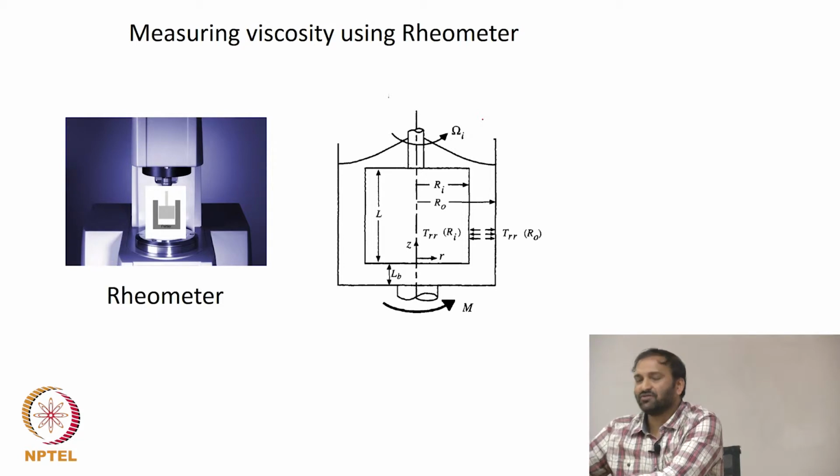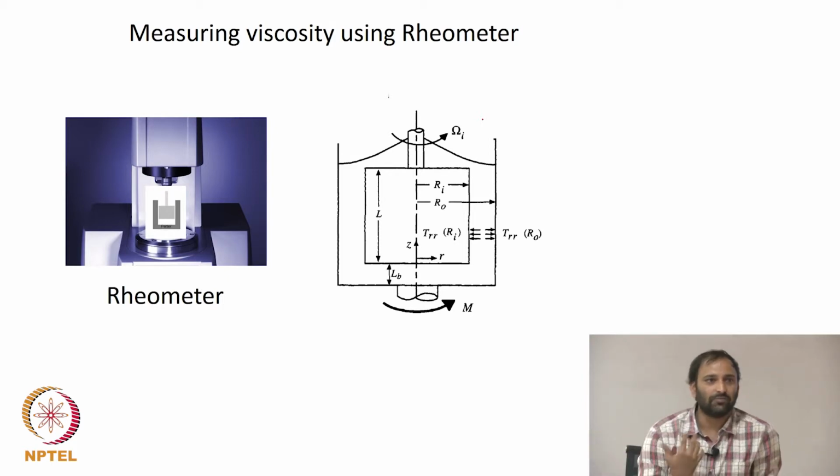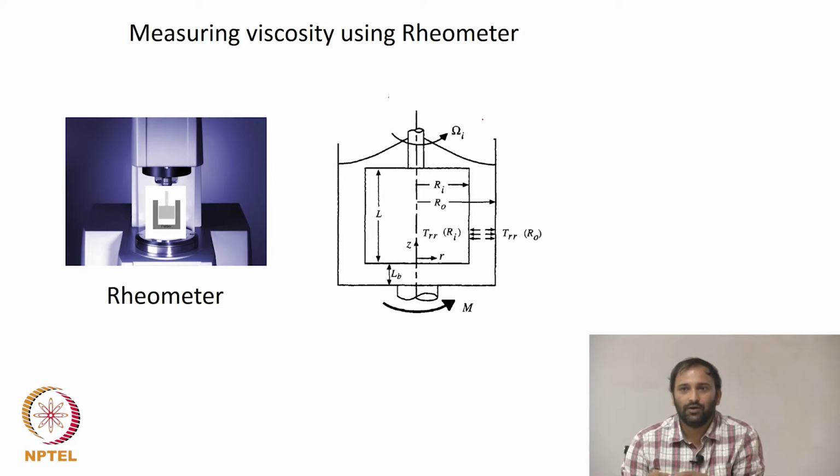In terms of the measurement, what the instrument measures is something called torque. Whenever something is rotating, you can think about the generation of torque. This instrument has a torque sensor, and it accurately picks up the torque that the instrument is applying. This is common for any geometry, whether you use a parallel plate, a cone plate, or a concentric cylinder geometry.